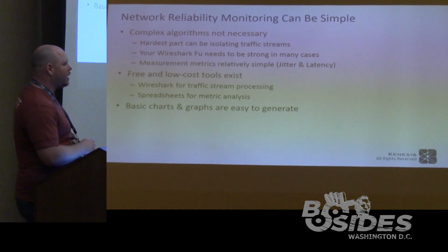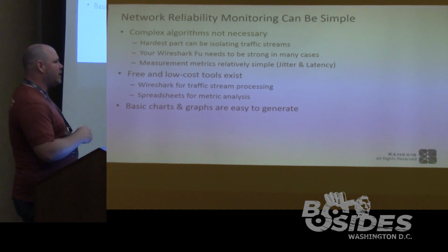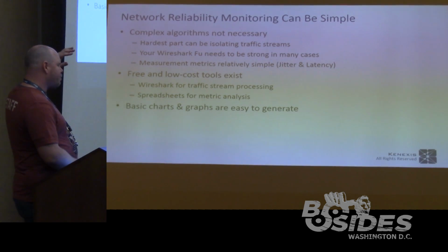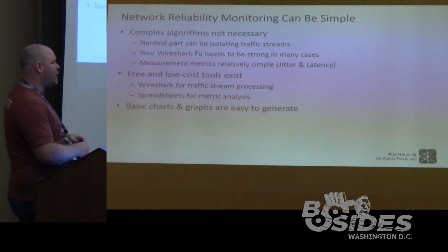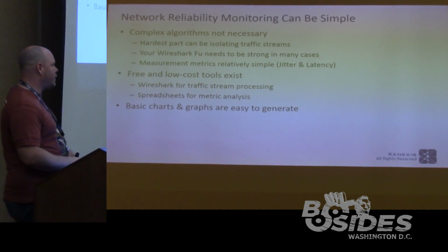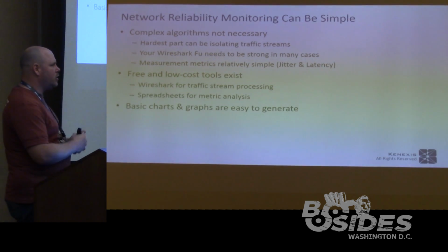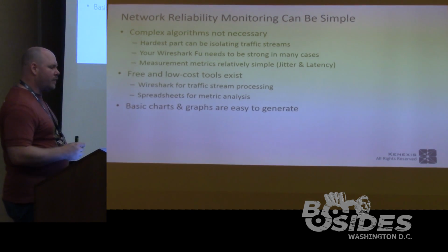As I said, Wireshark really has a lot of capabilities. I don't know if there was a Wireshark class here before, but you're not going to be able to use the TCP streams to follow industrial control system traffic. Generally, Wireshark doesn't know how to follow those TCP streams very well. What you need to do is get in and learn how to do your filters really well in Wireshark, and you can filter down to getting all the individual streams.